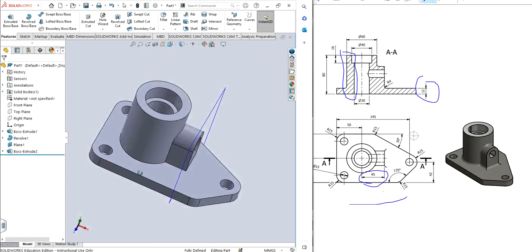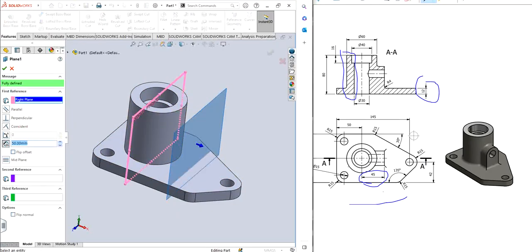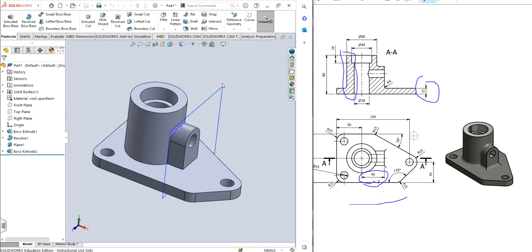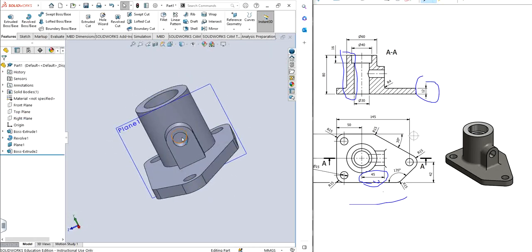So now the plane that I've offsetted, I haven't specified a value. So now I actually have seen that it should be 45 as it says right here from the center. So it's already at around 50. So 45 is the actual dimension that it was supposed to be. I'm going to change it. So there we go. So we have the entire thing done. We are missing a hole. It should be through hole. All right, as you can see right here.